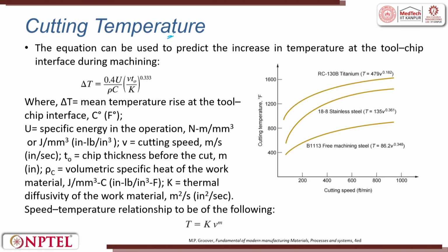So, the next topic of discussion is going to be cutting temperature. As I told you, cutting temperature is one of the very important phenomena because it is metal to metal cutting, friction there, and this friction deforms the workpiece, softens the tool, so you try to avoid it. So, it is always good to find out what is the cutting temperature.